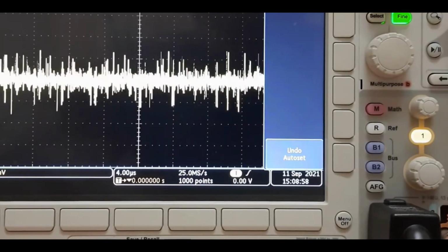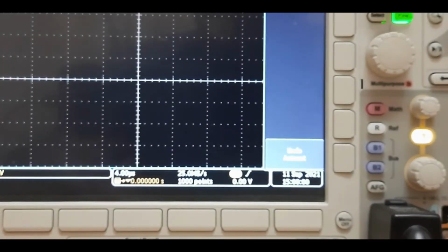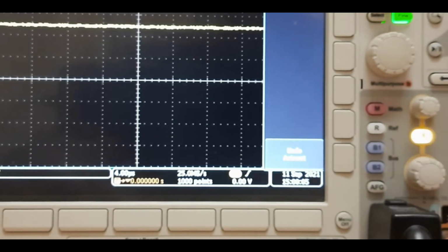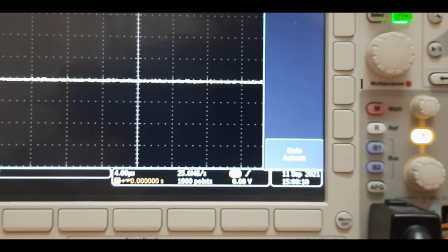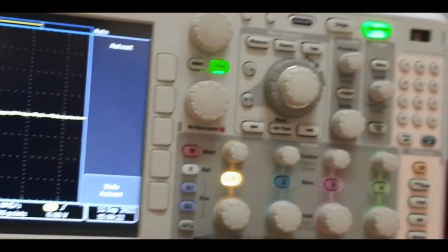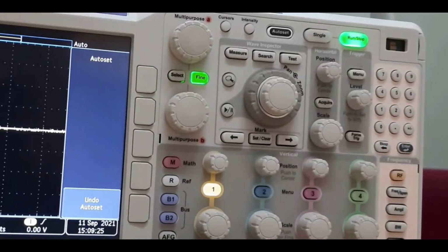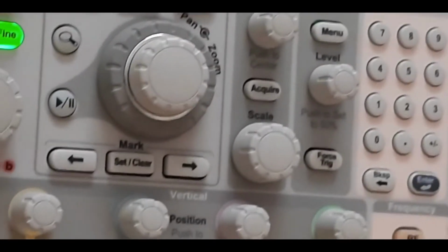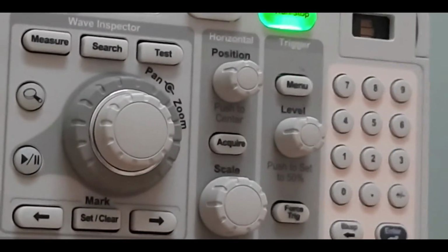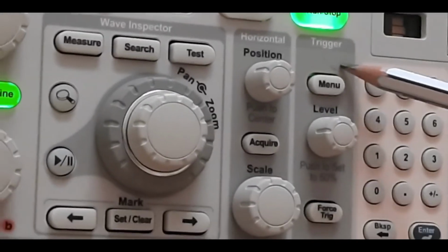So here if I press the switch, I can see 5 volt or 0, 5 volt or 0, but I am not able to capture the key bouncing event because that particular event is of very small period. So how can we capture the key bouncing using DSO? For that, remember, you will have to use a feature called triggering in your DSO. Here we have the triggering.